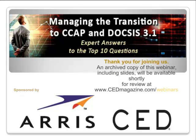Yes, Marwan, we have been doing work on characterizing all of the components of the RF plant, and we're actually now doing, we just bought some equipment to do testing of 4K QAM. The equipment that we bought can do 4K QAM on 100 megahertz of OFDM, and so we're actually going to be testing it in the actual plant. We're freeing up the spectrum in order to do that, so we'll do it in live drops and live plant. So yes, we're doing that, and it seems to work.